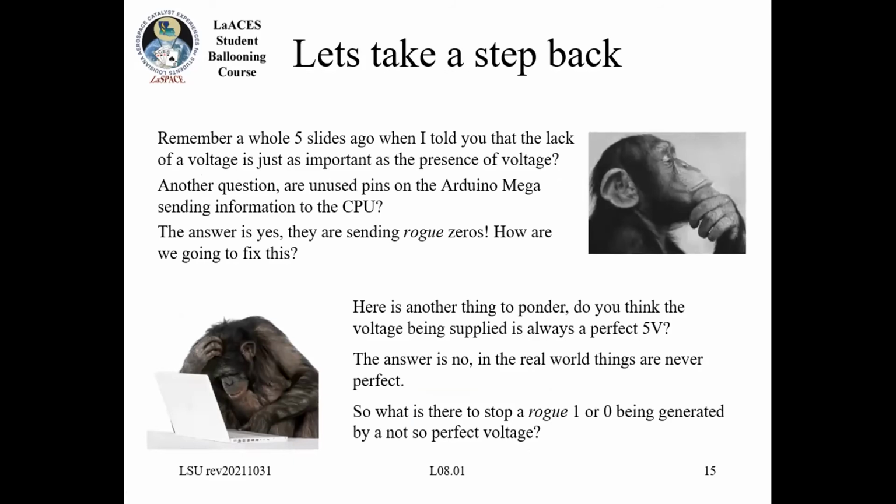So one of the things we talked about was, how do I tell that I'm actually sending a 0 or I'm just not sending anything, right? And you also may want to think about what happens if I read one of the pins. What is the logical value of a pin that doesn't have anything connected to it? Well, it may be a 0 or it may be a 1. This is actually referred to as the pins being floating.